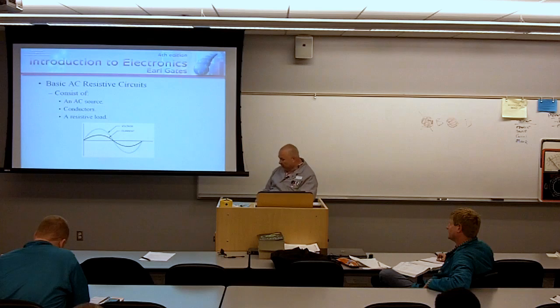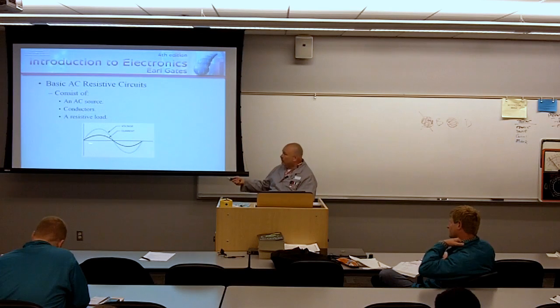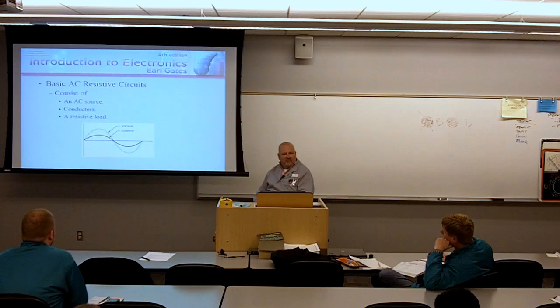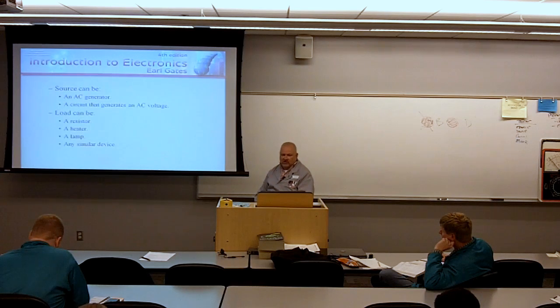Now what I'm looking at here is pure Ohm's law. When voltage increases, what does current do? Increases. When voltage decreases, what does current do? Decreases. When voltage increases in the opposite direction, what does current do? Okay? And as a matter of fact, degree for degree, they keep up with each other. So when voltage is at 90 degrees, current's at 90 degrees. When voltage is at 180, current's at 180. When voltage is at 270, current's at 270. Make sense? Get my drift? So we say that these are in phase with each other.